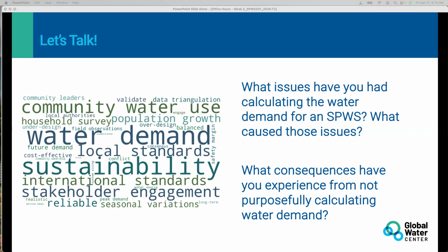So it looks to me like you calculate maximum water demand, you also calculate future use, that's when you add population growth. But then the value that is chosen as the planned design just takes the population demand and includes system losses.